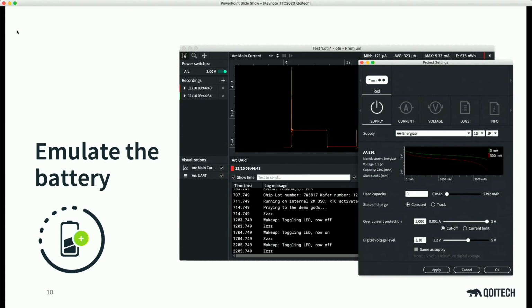Once you have done that, you emulate the battery, meaning that you use that discharge profile and play it on top of your application. So you plug in your device and play it on, instead of using a power box, which we all use. Our go-to thing is a power box and a datasheet, right? And this is what we want to change. Go and check your datasheet. It's good for comparison, a quick check.